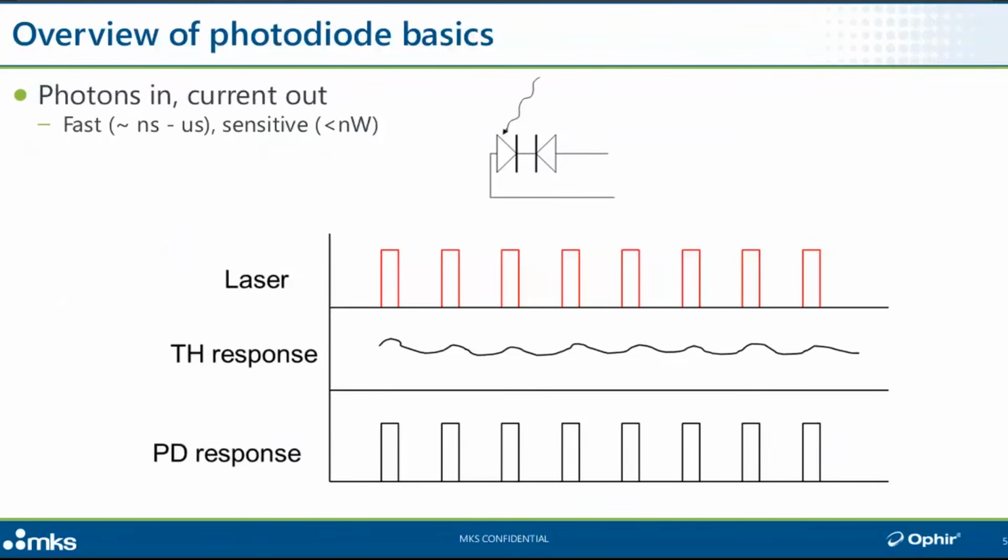Talking about semiconductor photodiodes. We're not going to get into the physics of semiconductors, but you basically have a PN junction. That's about as physics as I'm going to get. It's a device. Photons of light come in, creating a separation of charges. The electronics that are connected around this device turn that separation of charges into an electrical current, and the current is proportional to the power of the beam that came in. The constant of proportion is what we measure when we calibrate this thing. And that way you can eventually get a measurement. So light comes in, electrical current goes out, we get a measurement.